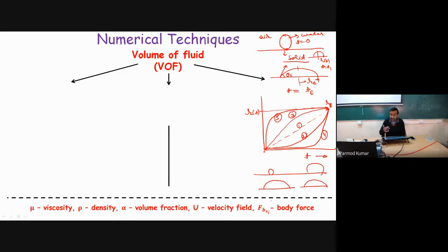If I am trying to do this for, say, spray cooling applications, then path number 4 is not good, because for the same amount of time we have less liquid contact. However, through path number 5, for the same amount of time we will have more liquid contact. That is something we want to tune, and we also want to know what path it is taking. To find out its accurate, detailed dynamics, because it has a direct impact on heat transfer applications, we want to perform numerical simulations.